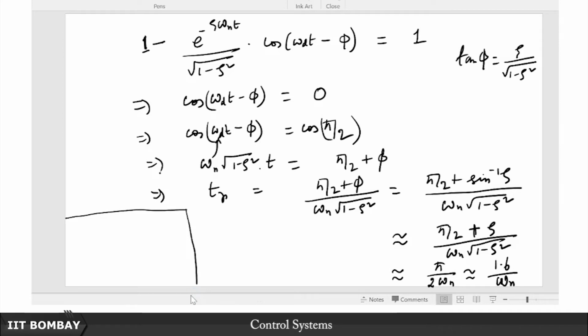So it turns out that with a lot of these plots and sort of an empirical computation, for overdamped or critically damped system it also hovers thereabout this rise time. So in general people come up with a single expression for the rise time irrespective of whether it is an overdamped or an underdamped or a critically damped system, and that is almost agreed upon by most textbooks to be 1.8 upon omega n.